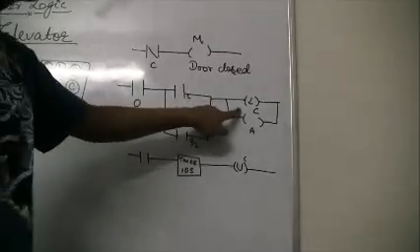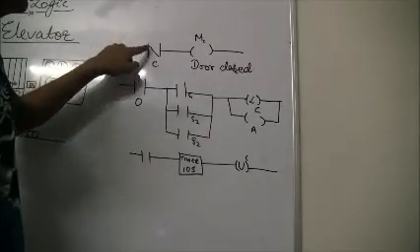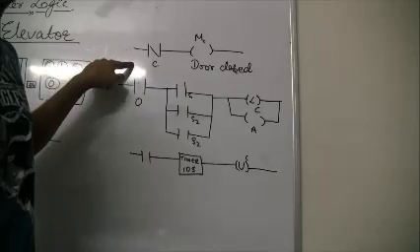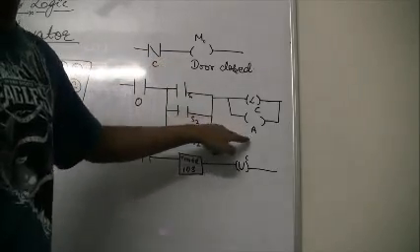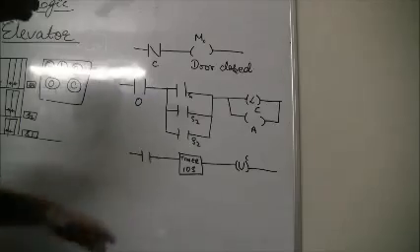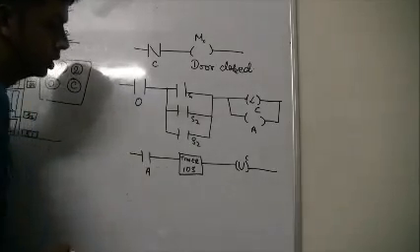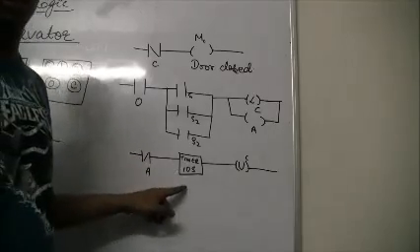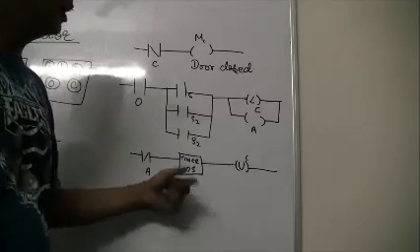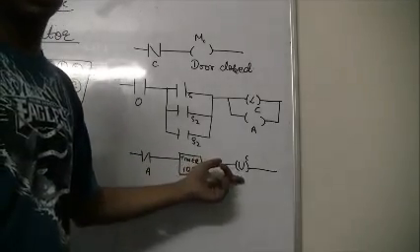When we latched C, this output, this was a closed switch which now became open, and the door is open, right? But it also powered an output A, which I write over here. So when A started, it triggered a timer of 10 seconds, and after 10 seconds the switch was unlatched.